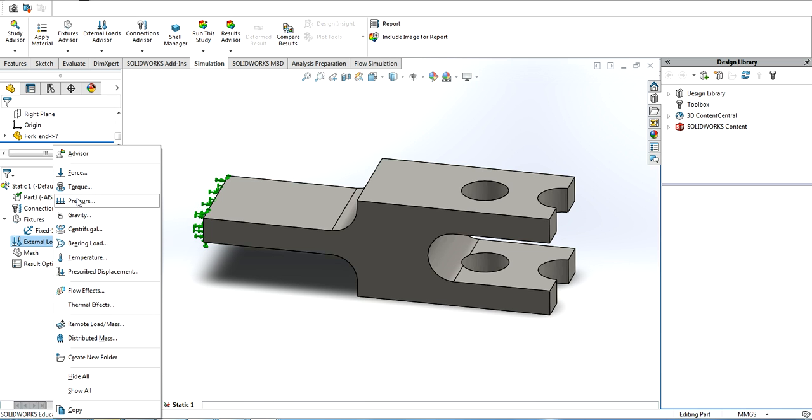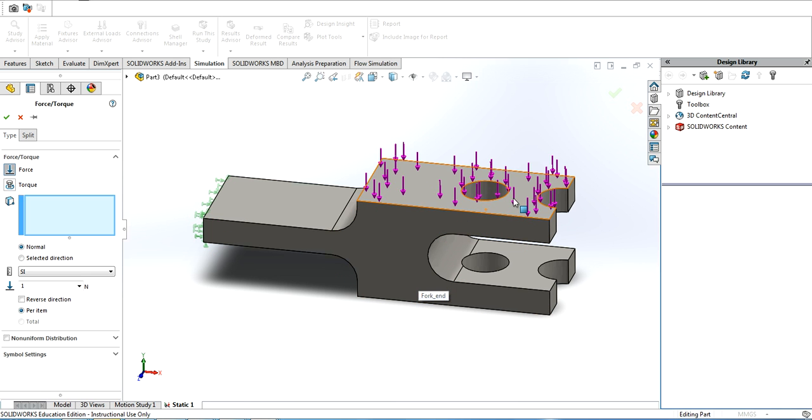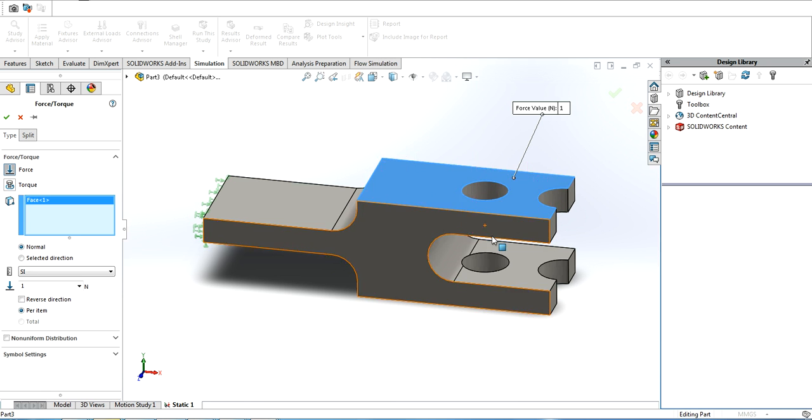This force is due to the pressure of the water. So this force is distributed. It's not a point load, it is distributed. You have to define distributed. For your case here, just make it a very general, simple case. Say for example here you can apply it on a surface, side surface, on edges. You can apply it in different directions. Say for example I apply it on this edge as an example.